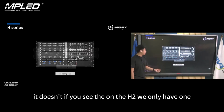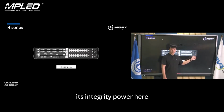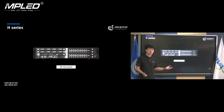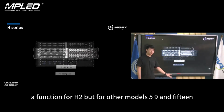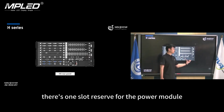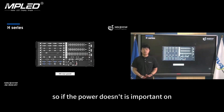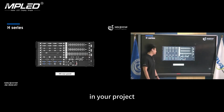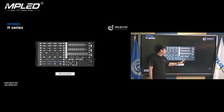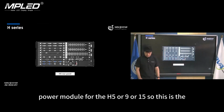The power redundancy: if you look at the H2, we only have one integrated power supply here. So for the H2, there's no power redundancy function, but for the other models, 5, 9, and 15, you can see there's one slot reserved for the power module. So if power redundancy is important in your project, when you place the order, you can add one more power module for the H5, 9, or 15.